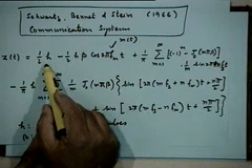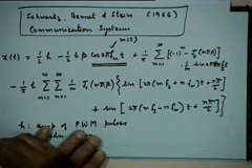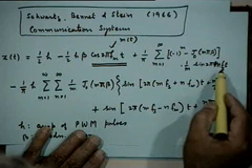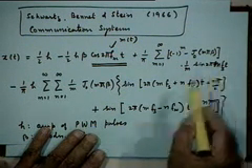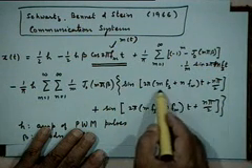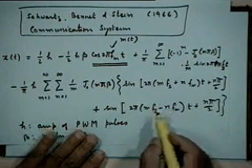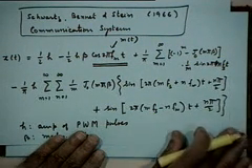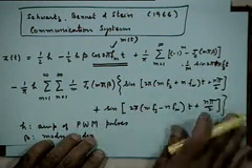What you will notice is that this signal has a DC component, has the desired message m(t) as one of the additive terms, and then has components corresponding to the sampling frequency of the pulses, as well as sum and difference of these frequencies, m fs plus n fm and m fs minus n fm, right? For all possible values of m and n. And of course the amplitude of these components will somehow depend on the Bessel function values, right? If you want to plot this, the spectrum therefore will look something like this.